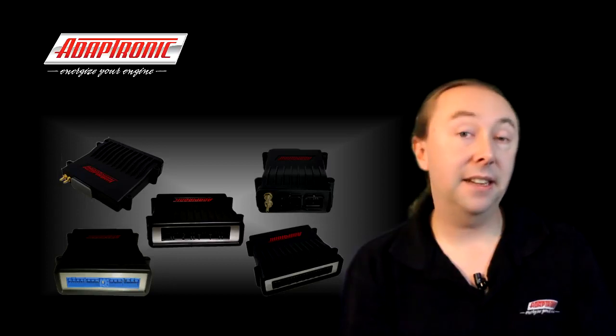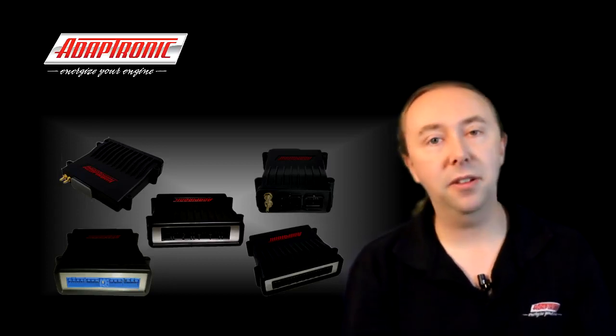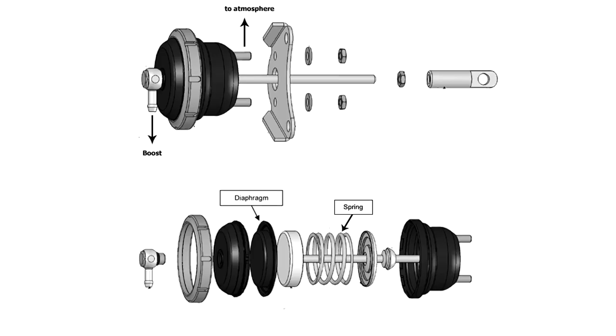Now apart from this undesired effect, the real thing that's supposed to control the wastegate being open or shut is the actuator, and the actuator is a servo diaphragm where you have pressure on each side of the diaphragm, and the pressure difference across the diaphragm actually controls how much force is activated. Now there's also a spring which holds the wastegate shut, and that spring has a fair bit of preload on it, and that preload is called the cracking pressure if you like, because once you exceed enough boost to overcome the preload of the spring, then the actuator rod starts to move and the wastegate itself starts to open.